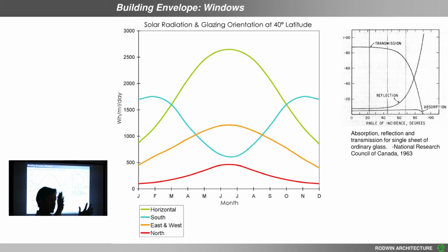Really good window that looks right at the mountain, but it's the quantity of glass. So you're going to have less west-facing glass because you can't control the heat. We're going to take as much of the glazing as possible, as much of the windows as possible, and put them on the south because that's where we're going to get better energy performance. It's all a matter of priorities when we design and build, and in this particular case, we're prioritizing sustainability over just the views or other factors that, like privacy, that most people consider when building a house. So it's a different way of thinking about design.